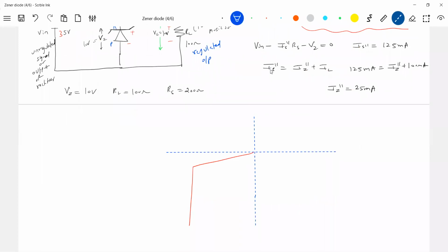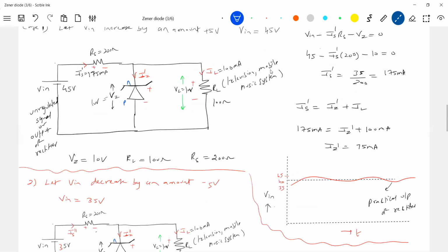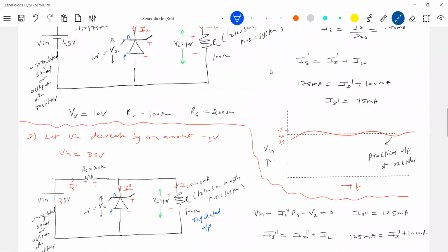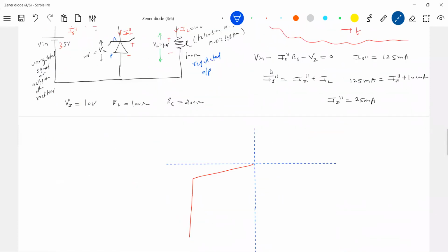Slowly, so let's give the priority for that. What should be the minimum current? How much is it? 25 milliampere, no? Where is IZ? IZ is how much? 25 milliampere. So the Zener diode, what I pick up, if it is having some characteristics curve like this, if 25, no, let me make it 20 milliampere. I'll be on the safer side. Then,